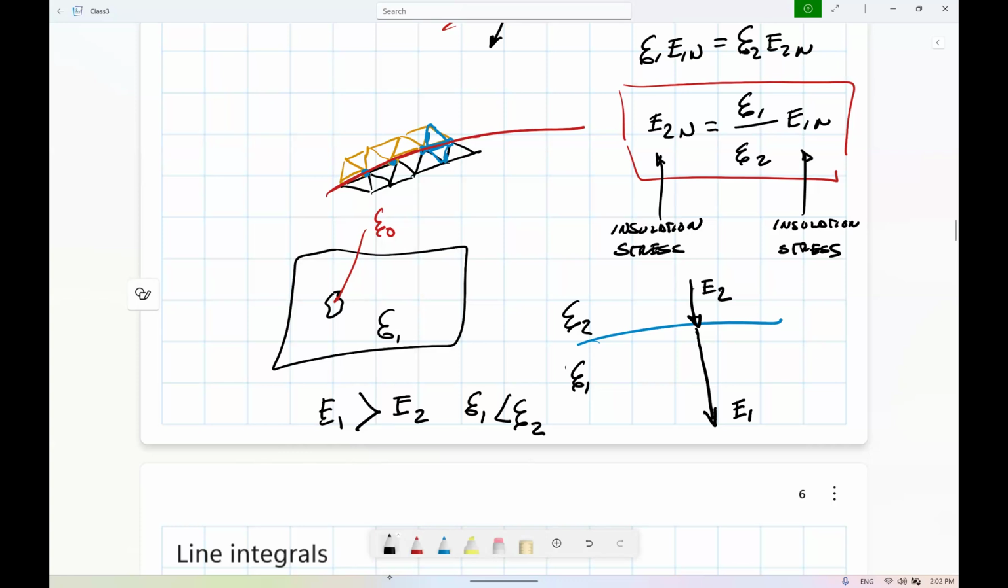So oil will move and take the heat from wherever it's being generated, either by natural or forced convection, and it is going to exchange this heat from wherever it is being created to the outside. All right. But that forces you to have at least two different insulating materials. So now you're going to create stress because you have two different insulating materials. My question would be, how does the stress distribute in the materials?